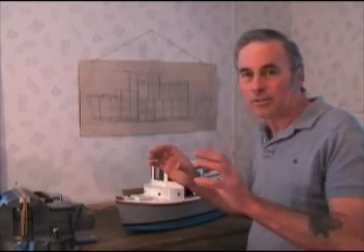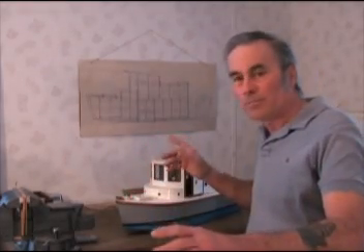Sometimes you get confused, sometimes I get confused. That's why I have P's and S's on the building stock, for port and starboard, so I don't have to think about it. The parts marked P go on the port side, the parts marked S go on the starboard. In timber, it'll go across the boat. I'll have a P on one side and S on the other. And on the stringers, I'll have a P for the port side, S for the starboard side, and arrows. Arrows are always pointing forward or up.